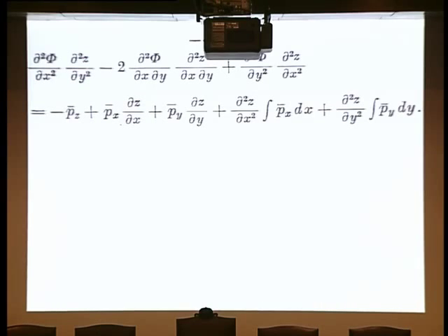Again, this need not concern us deeply, but I'm going into it because it is the signs associated with this term and with this term which determine the whole characteristic of the solution. This essentially is the curvature in the x direction, the amount of curvature of the vault going like this. The other one is the curvature in the y direction, the curvature like that. And if we are standing inside a dome, then the curvature there and the curvature there have the same sign.